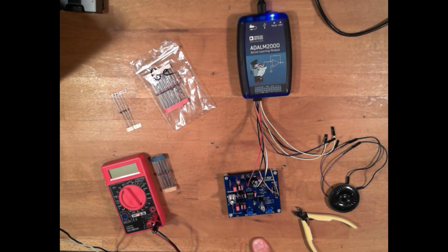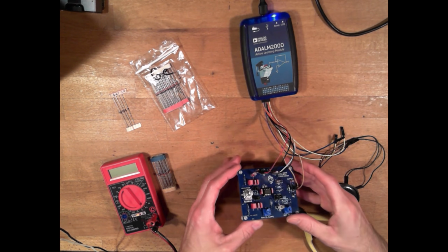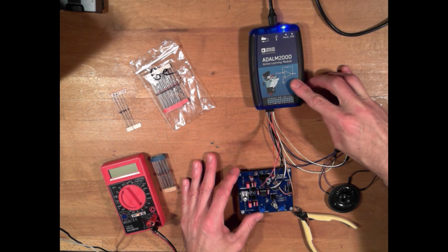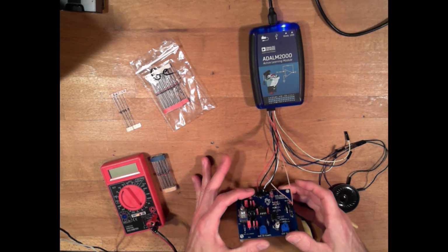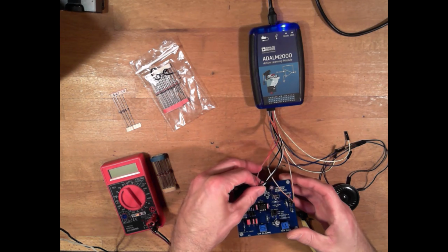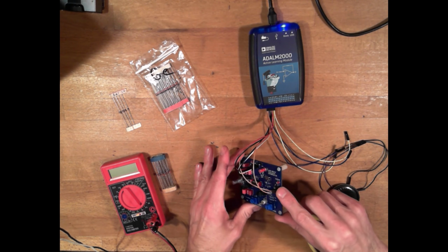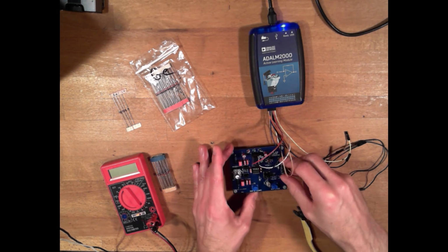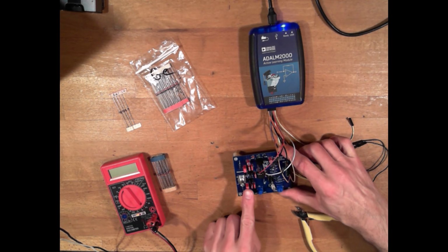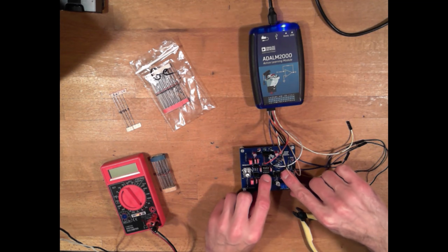Okay, we are ready for a power up check here. So I have connected the Wien Bridge oscillator to my ADALM2000, which we will call the M2K from here on out. I've got the positive supply, 2 ground wires, and negative supply hooked up to the headers here. And then channel 1 of the oscilloscope input is connected to the output here. I've got the range capacitor set to the center 0.1 microfarad, and I've selected the diode clamp gain control method here.